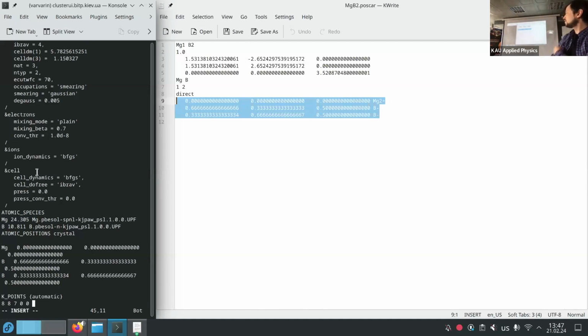At first glance you can take the k-points so that you multiply celldm(1) by the k-point number, and if you get about 40, it's a rather good number for a first shot. It's not a physical rule, just an empirical rule. Is the syntax correct? I think so. 0 0 0 0 means that we start from the gamma point. Now escape, and you can save it.